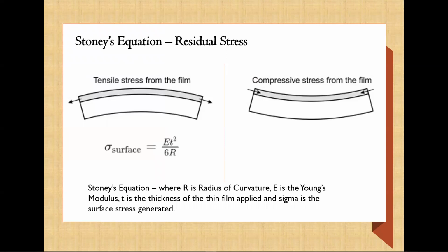All right, so how can we quantify this residual stress in the thin film that we create? Well, we would use Stoney's equation as a known example to find residual stress effects for thin film coats. And since we know that additively manufactured metals are created via the thermal heating and subsequent cooling in the material, there's actually a thermal gradient here during the buildup.